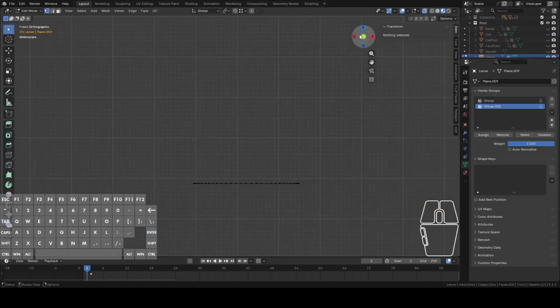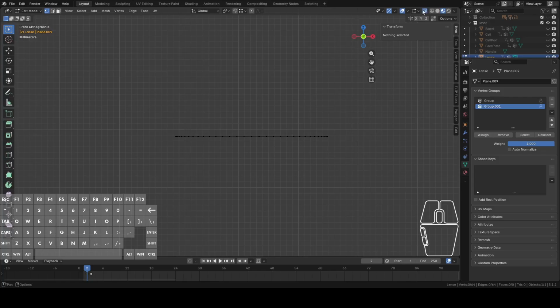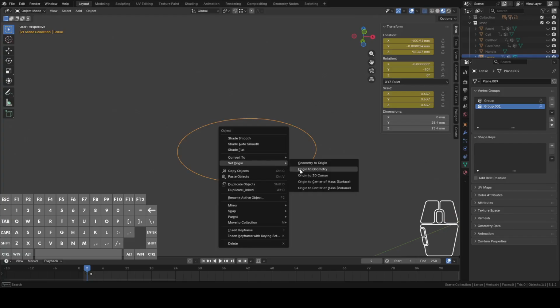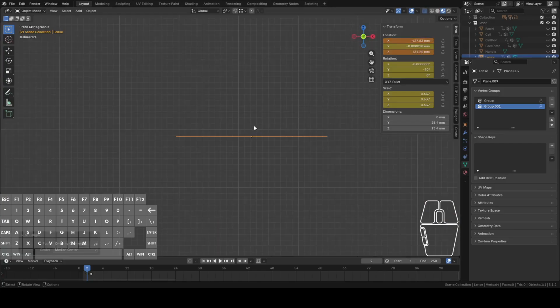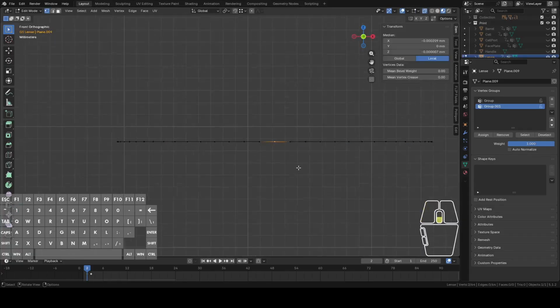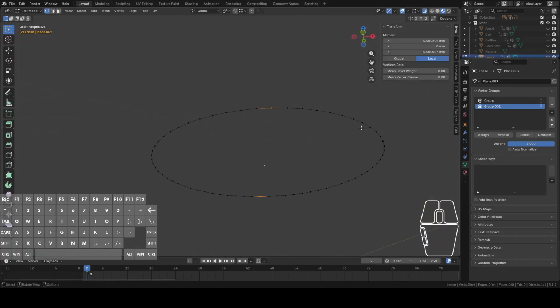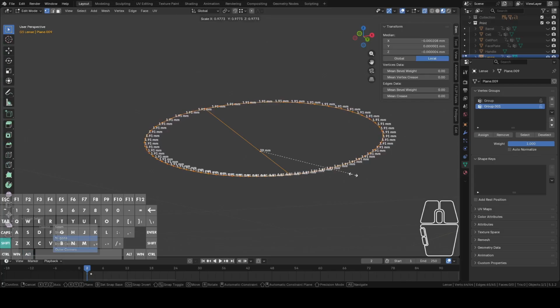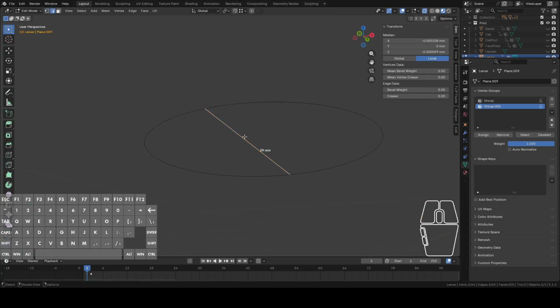And the first thing we're going to need to do is shrink it by about 0.5 millimeters. So let's right click, set origin to geometry to get that point right in the middle so we can see exactly where it is. And we can select these vertices with X-ray mode on, both of them, and hit F to get that edge length. So now let's take 0.5 from every direction. Let's go ahead and just make this 39 millimeters wide. So we're going to select everything with Alt left click and then S, and we're just going to shrink it down with S for scaling. And that's about where it needs to be. We can get rid of this edge now.